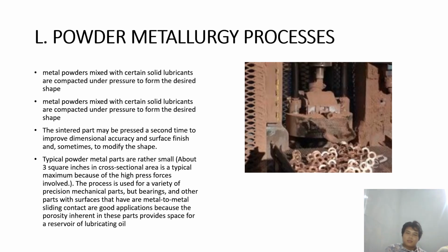Metal powders used for parts production can be a combination of various elemental particles. So with powder metal, we choose the powder depending on what you want the metal to be. In pre-alloyed powder, the proper proportion of ingredients is already present in each particle. In either case, additives such as binders and lubricants are usually added. The powder is then consolidated in molds or dies. Okay, we're gonna talk about this later.